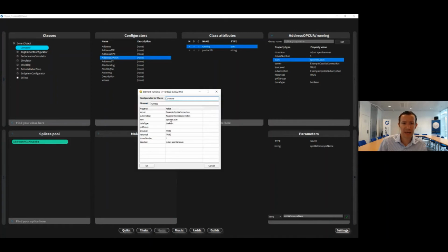If we edit back in here, I'm going to add that as a parameter here. Now let me just switch that around and put it to the beginning. That means that this part of the string between the curly braces can be substituted later on per device instance. So it's no longer a static text, it's actually going to be a dynamic text which can be defined for each conveyor that we create. Okay.